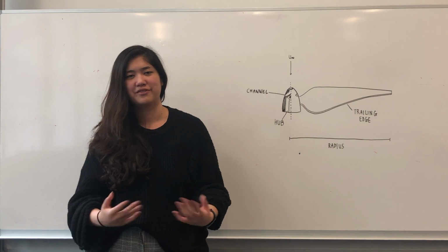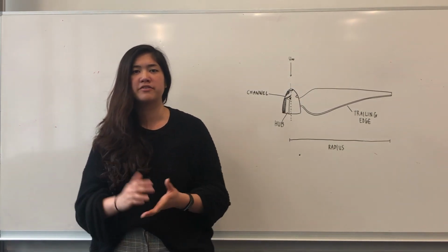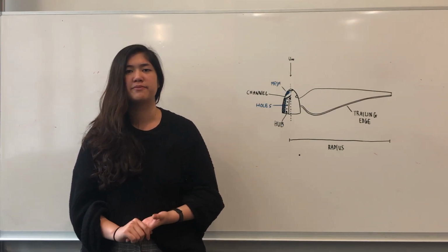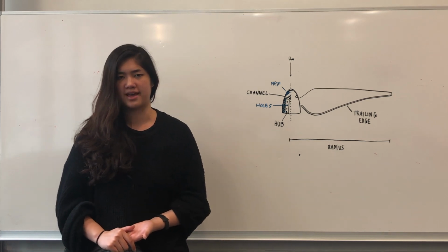If we happen to fail this year and have one more chance of building a wind turbine under the same constraints, we will likely stick to our 2-bladed design, but there are a lot of improvements that can be made. There were 4 main adjustments we could have made in our design, all of which were because of our reluctance to take massive risks. The first adjustment we would make would be to the nose cone and the hub, which could have been modified much more carefully by implementing a mesh design instead of printing it solid and drilling holes into the hub to reduce the mass.